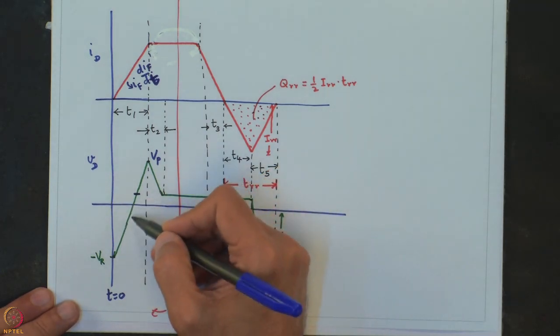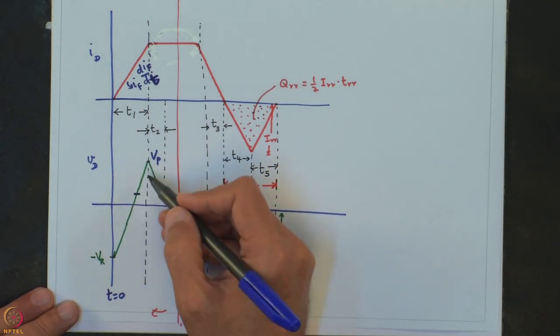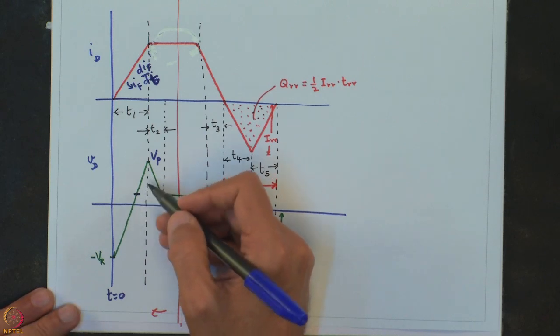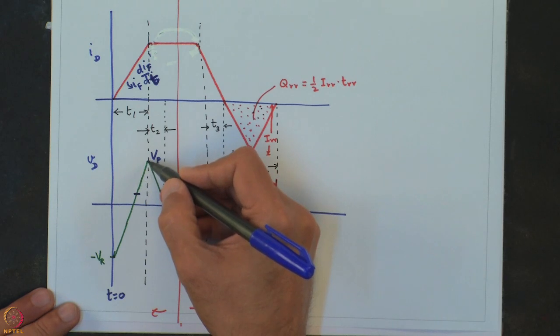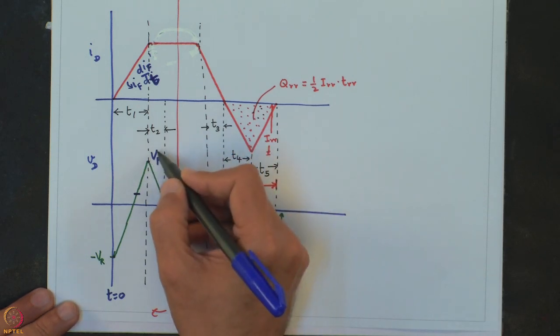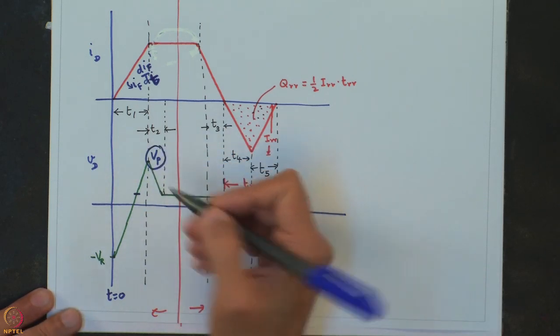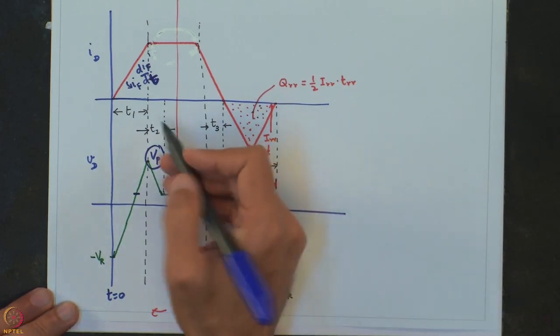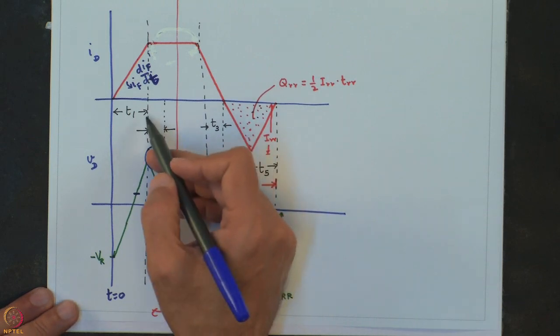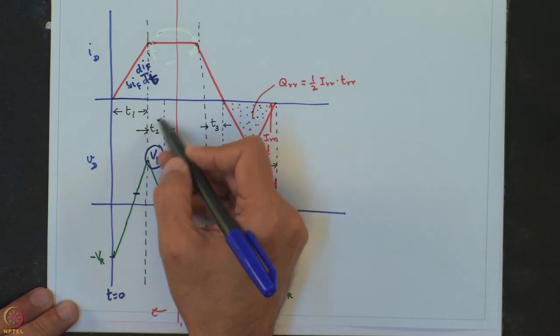Secondly, there are stray inductances on account of the silicon wafer as well as the leads. So, this voltage you see actually tends to overshoot, and I have marked this as Vp, it actually reaches a value which is Vp. Now what happens at the interval after T1? So let us mark this as T2.